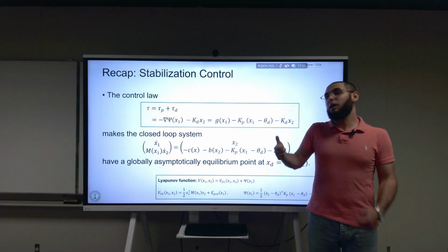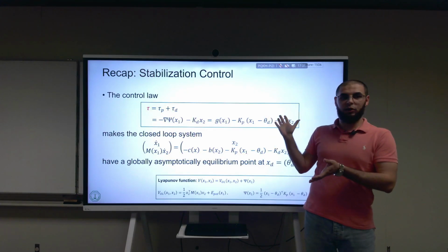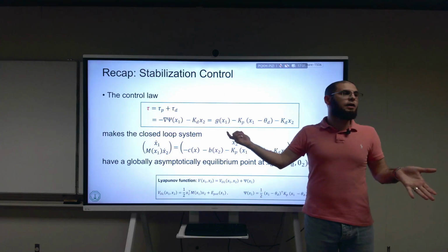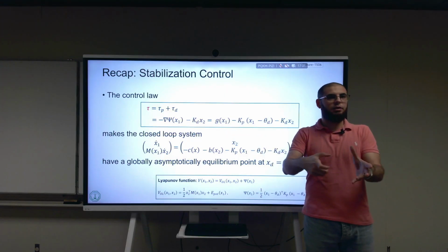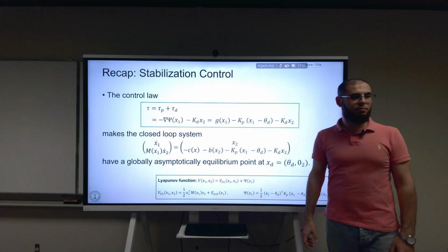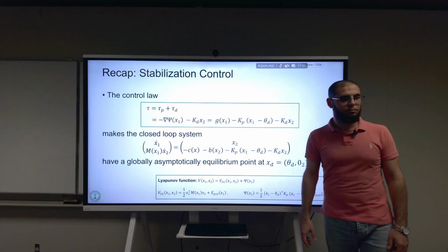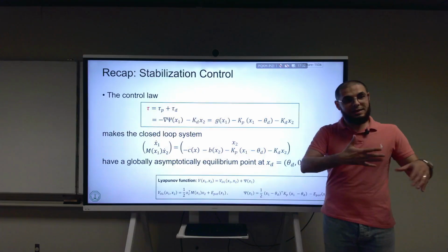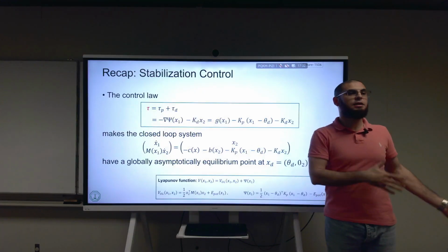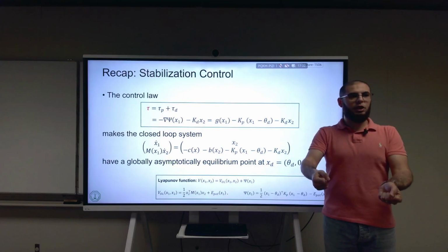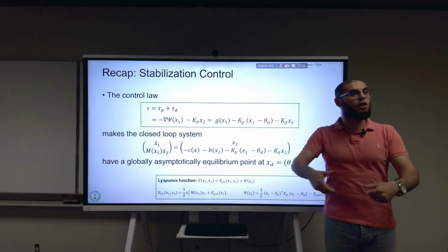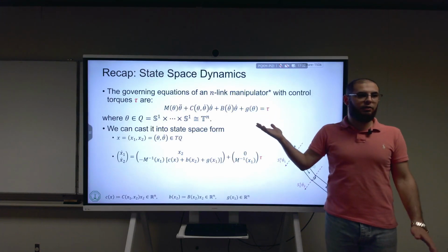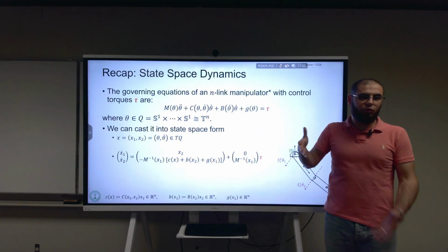If you apply some brakes, and that's something we didn't model here, they're not modeled in the equation, then already you don't need to apply any torque because you're clutching the mechanism. So if we applied brakes, we should cancel the GX1? No. This is how the system dynamically moves. The brakes is something else. Brakes is after you reach that, you just clutch it, and the dynamics, if you have brakes on, are all zero. You don't move. Even this equation no longer is valid, right? If you're applying brakes, you're not going to be moving.